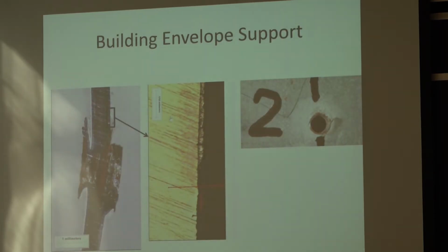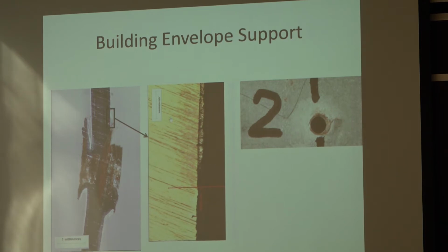The second issue, if I can add about sheet galvanizing for cars, is when you have an accident. It's one reason why the repair is never going to be as good as the original construction, because if they come and do some sanding of the surface, welding, whatever happens there, it typically doesn't receive a galvanizing treatment after that. So it's going to rust easily. And that is because the galvanizing is only going to protect you over a small distance.